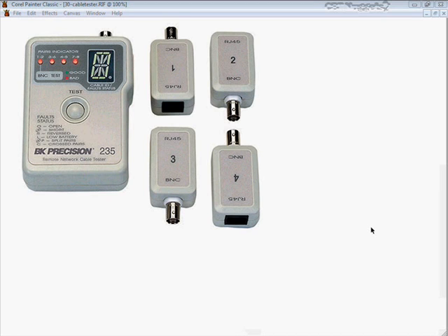They usually have a combination of tools, testing the source of electric current, a voltmeter, and some way to test all the contact points in the cable. These can do a continuity test where current is passed down the connection, and if there's a current, the connection's assumed to be a good one. There's also a resistance test where a known current's passed down the connection and the voltage that shows up is measured.